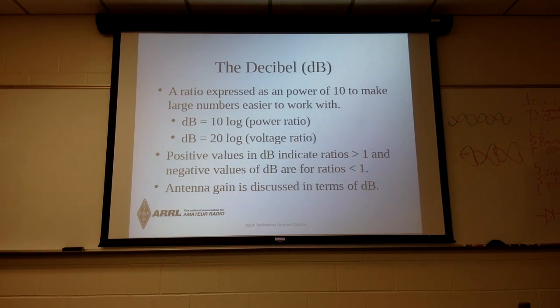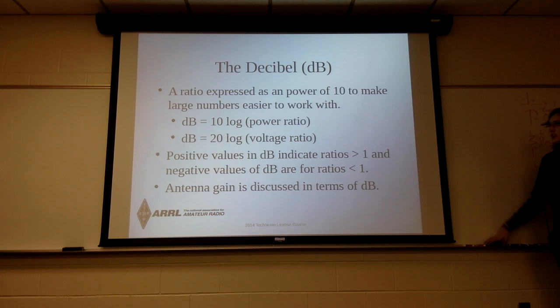Okay. Speaking of dB, remember when I said we actually do use deci a little bit? Well, here it is. All you have to know for decibels is they're an easy way to multiply numbers without actually having to multiply. Instead of multiplying 100 by a million, which is 100 million, we could say that's 20 dB plus 60 dB. 60 dB is a million. 20 plus 60 is 80. Boom, there you go, 80 dB.